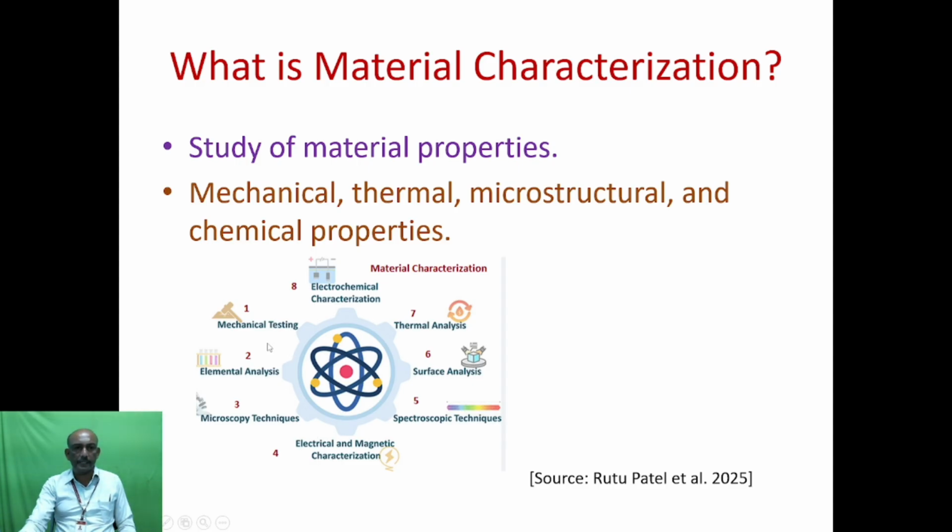First, the mechanical testing. For every result, for example, if we get a tensile strength for a particular material of 150 megapascal, and in another condition we get 200 megapascal, what is the scientific reason behind the enhancement of the tensile strength? It is analyzed using elemental analysis. Elemental analysis means each element, for example, what the major elements are, magnesium, aluminum, zinc, nickel, chromium, and how much percentage is available in that material. Using microscopic technology, using XRD, SEM, EDAX, everything, we have to analyze the microstructural part.